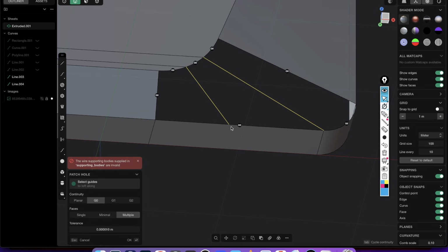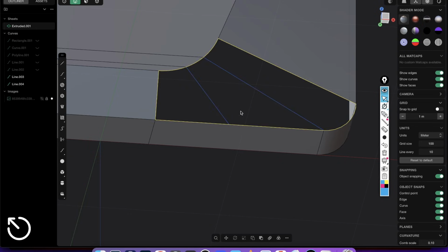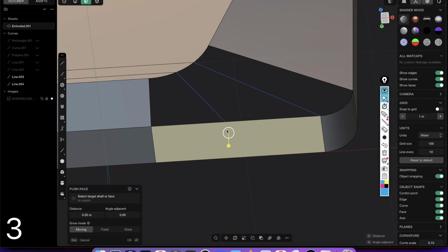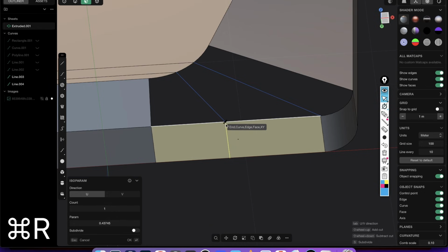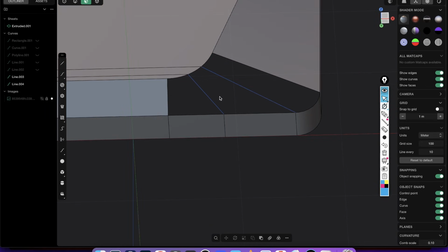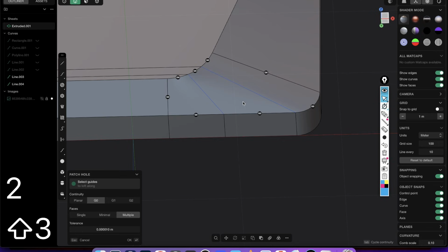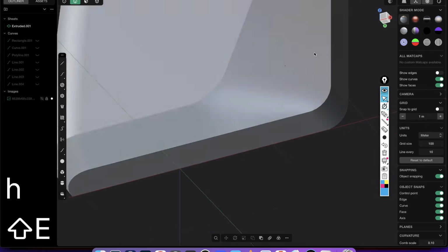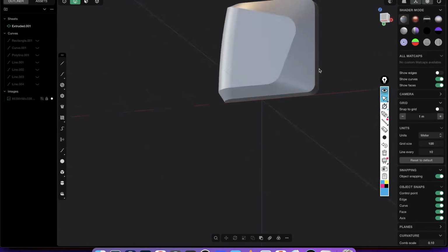And again, I did a little mistake because I'm recording, excuse me. So select 3, face, and obviously we need here an edge 2. So isoparam, just break that. And now it will work. Press 2, Alt click, patch it, Shift, bam, G1, right click. Let's hide our guys here. And voila, look guys, isn't that nice?